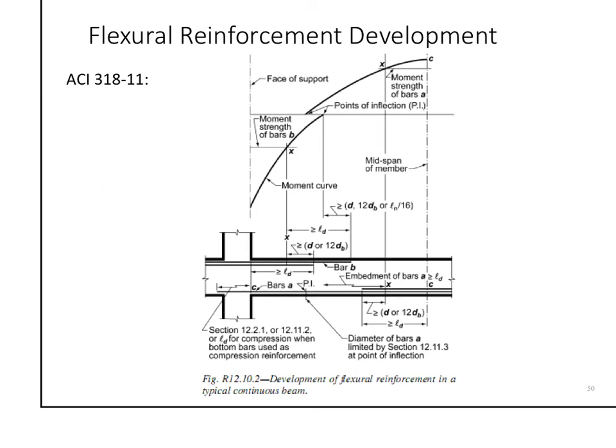Imagine that I have high demand on one side here. You can imagine this is the top reinforcement, so this is a negative moment. That one here is the positive moment. If I have here two parts of the bars, so imagine that I have here, as I said in the example, 3 bars that will continue and 2 bars that will stop.